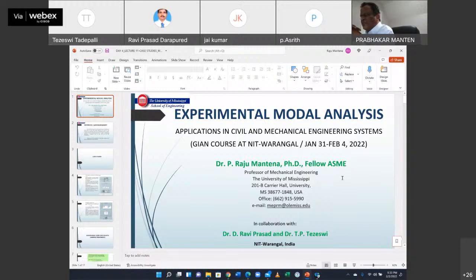Yes, that's the amount of energy in the content. You can get it from the overall spectrum pattern. You can compute the total power spectral density. That's got to do with the mobility function and all that. All those combined together will give you an overall figure of how much energy is in that content, and that's referred to as the power spectral density. Mathematically, there are some relationships. I don't have them with me, but it gives you mathematically what it is, computed from the frequency response data as a separate parameter. And it's a good indicator of how much energy is taking place in that particular mode of vibration. Thank you, sir.